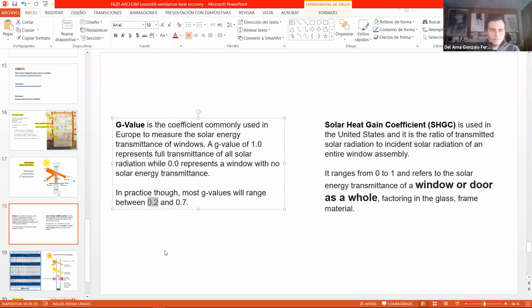It depends. You have to think twice before deciding what kind of glass. It doesn't matter which one, no, think about this. And it's not only about the U value; we always have to reduce the U value, in hot countries or cold countries. But when it comes to the solar heat gain coefficient, we have to think twice.